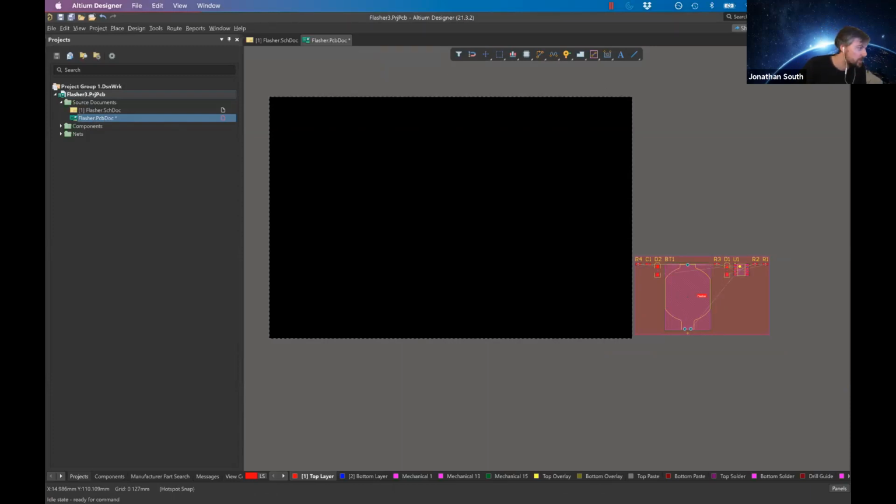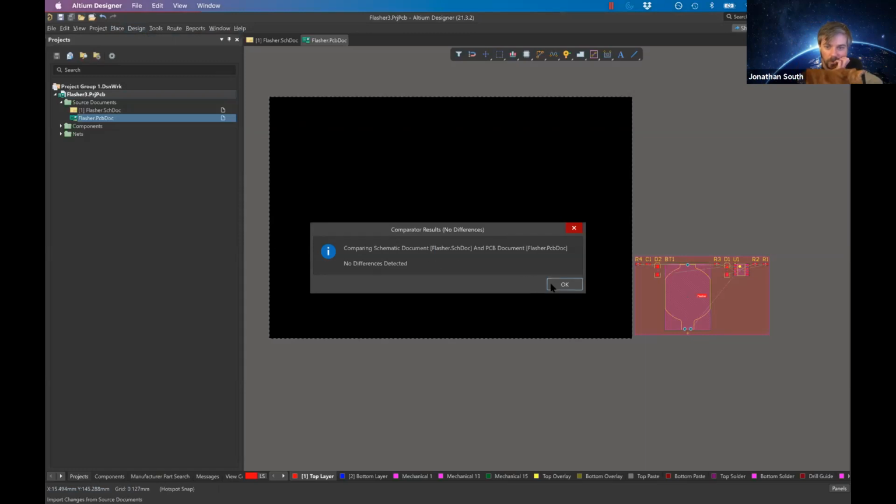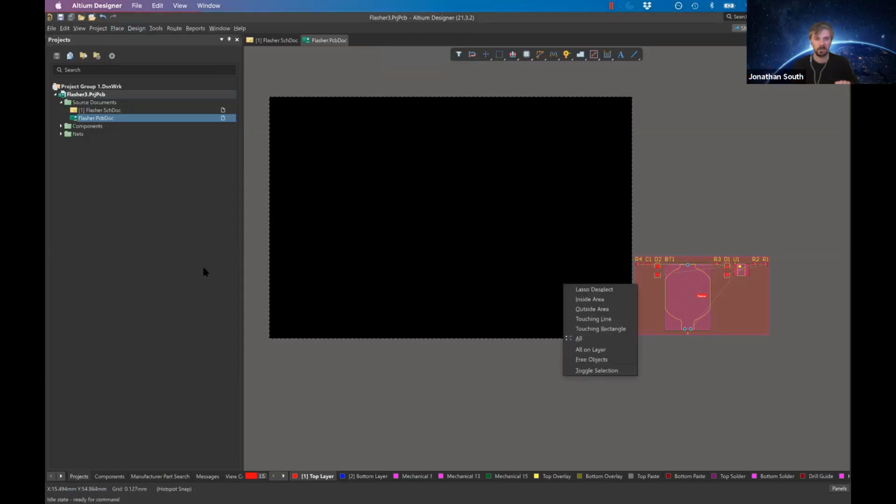Yeah, okay. And is your PCB document called PCB1.PCBDoc? Just checking how it's named on yours. If it can't locate the document, it probably means that there's some sort of sourcing issue. I don't know exactly what that would be. Have you saved? I take it you've saved it. Design, import. Yeah, not sure what could be the issue there.